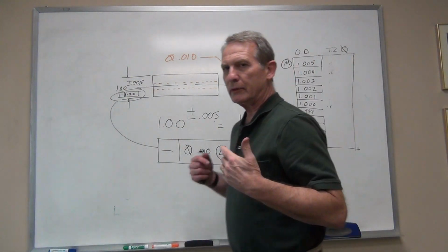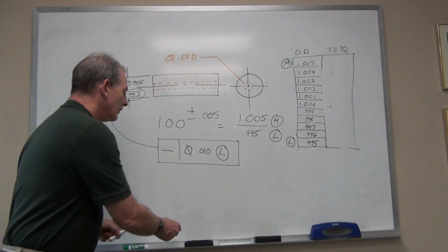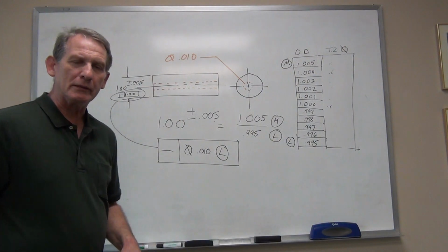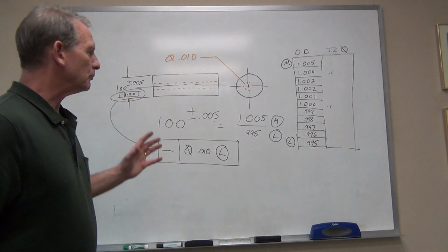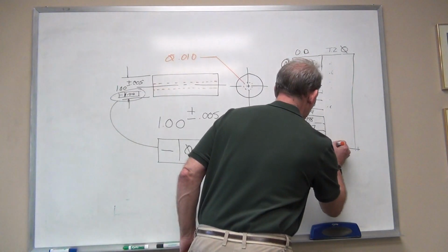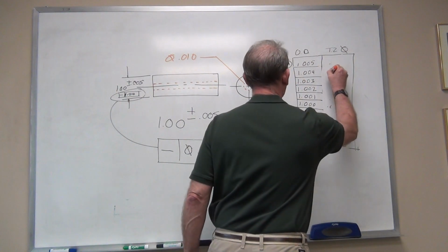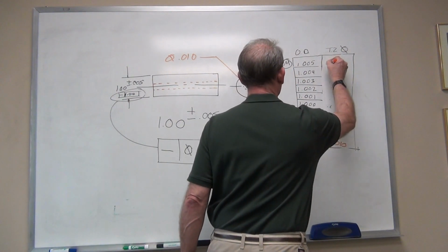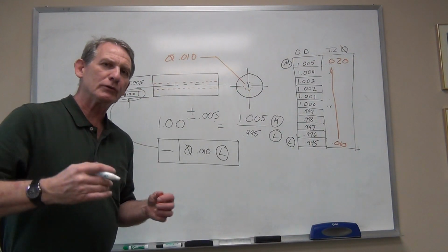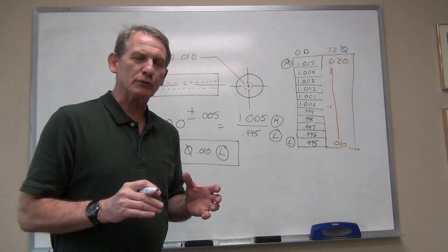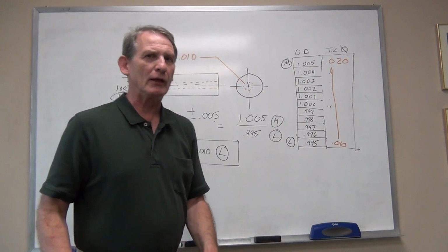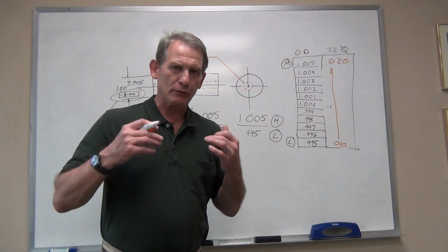if you say it out loud, it'll become obvious to you that I have a straightness tolerance zone of 10 thousandths when the feature is at least material condition. So when this shaft is at the smallest, I get the smallest tolerance zone. And so on and so forth, a thousandth at a step. So if you want to have the most tolerance zone for straightness, in this case, with the least material condition modifier, you would have to make the shafts at their maximum material condition.